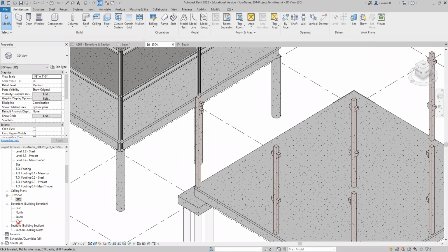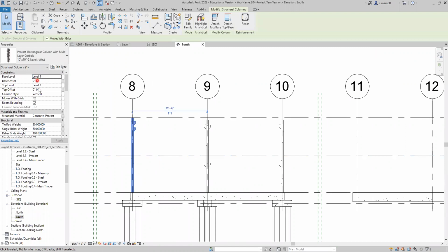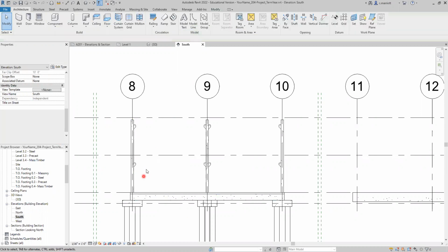Okay, we got it from the south. That way we can take a look at the heights, click on it. Base is fine. This should be -8, not -4, -8. And then we can scroll down and adjust those heights. Let's see here, the east side in this case will be 1 foot 8. And this number 2 will be -13. Okay.